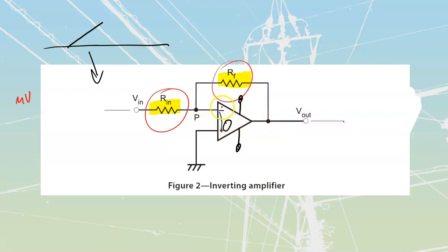Now, because we're coming in on the inverting, it is going to drive this end down. So it's going to start to switch out to this, where I'm now going to see on my output side, my value of voltage start dropping like that. As my value of voltage drops over there, this feedback resistor over here is going to start to drop volts, but it's going to move into the negative region.